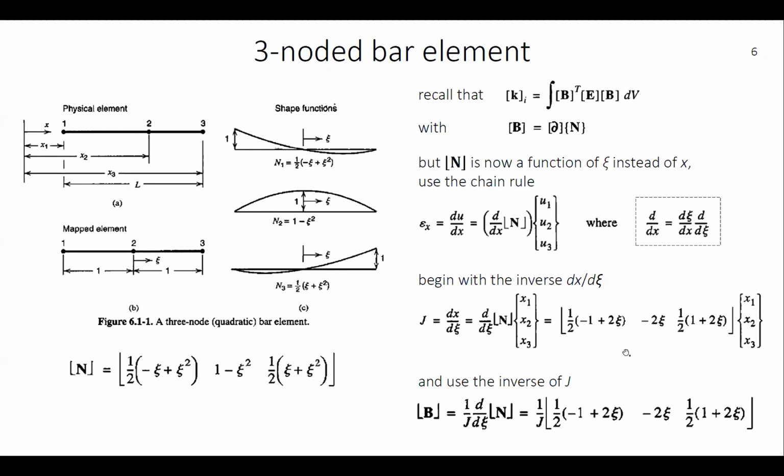So we take the inverse, we call this J, which is denoted as the Jacobian. And the Jacobian is a matrix of first order derivatives, which is just a general mathematical tool, if you like, which is illustrated here. So this is the first derivative of this function N. We take the inverse of all this. Just for short, we denoted J here. So we have 1 over J, which gives us dc/dx, which is this first part.